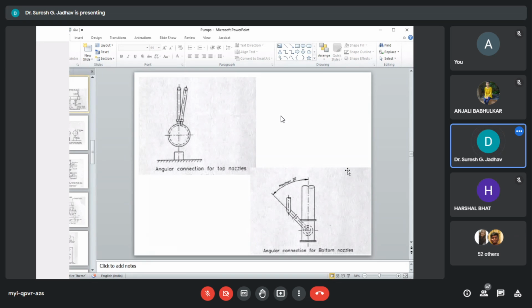We'll see the first advantage: if the hotter liquid is allowed to flow through the tube, this will minimize the heat loss and avoid the use of thicker shell insulation. If high pressure fluid flows on the tube side, only tubes, tube sheets, channels, and covers have to be designed for high pressure, and this reduces shell side thickness and the cost.